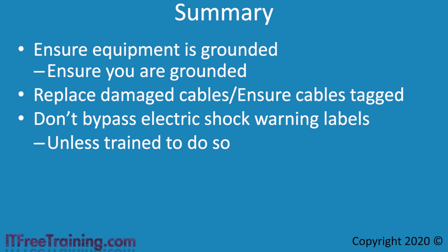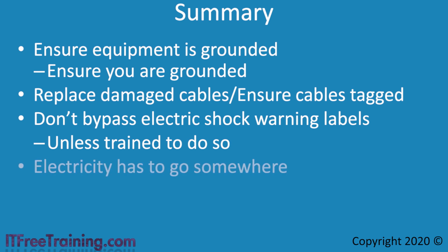Keep yourself safe. Lastly, remember that electricity has to go somewhere. I like to think of it like water because it acts in a similar way. Electricity will take the path of least resistance. Hopefully, it does not find you being that path of least resistance. Make sure your devices and workbench are grounded. It may not stop you getting an electric shock, but hopefully it will reduce the effect it has on you.